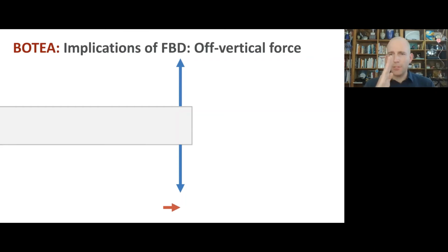Maybe the robot heading has shifted a little bit so that that gravitational force on the payload encodes a small side-to-side force. Well, what we should see quickly is that we don't have static equilibrium. This is going to want to spin counterclockwise as I've drawn it. And we can easily have force in the opposite direction and want to spin clockwise.